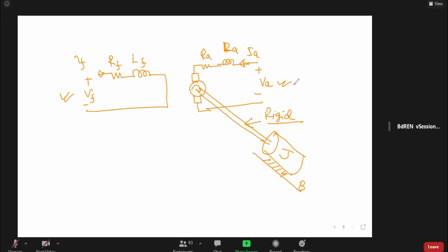Which strategy is followed where? Do you have any idea? It is supposed to be taught in the second year when you have been introduced to DC machine. Field weakening process is used up to a certain point. Beyond that point, you cannot use your field to raise your speed. You have to use another technique there. Because I cannot teach you everything. If there is something you need to know, you explore it on your own, okay? Yes, sir.